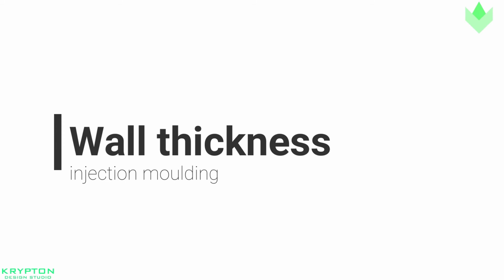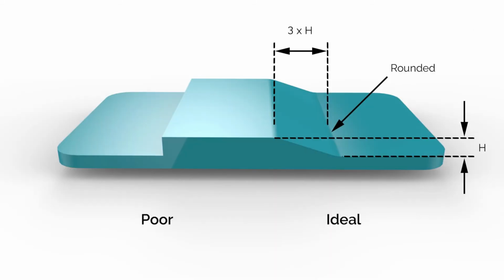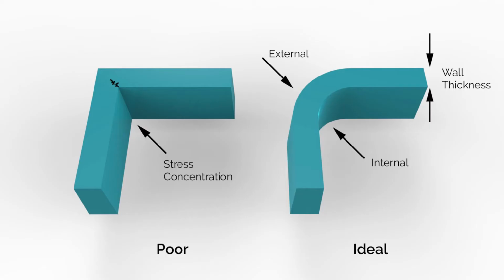Wall thickness. After ejection from the mold, injection molded parts are cooled down from manufacturing temperatures so that they can hold their shape when ejected. During the part cooling step of the molding process, change in pressure, velocity and plastic viscosity should be minimized to avoid defects. Few aspects are more crucial during this period than wall thickness. This feature can have major effects on the cost, production speed and quality of the final parts.